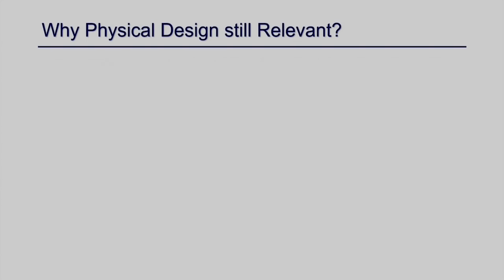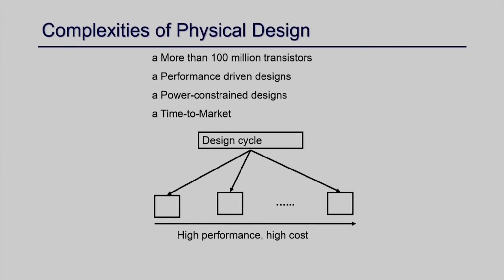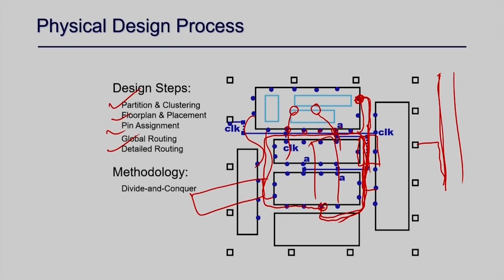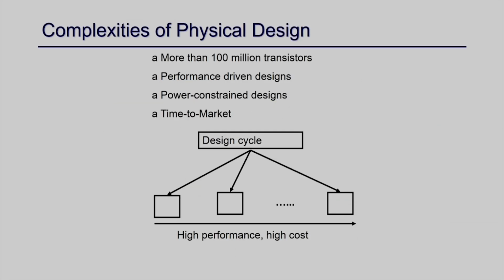And also one more important point has to be noticed here, that all these subtasks that I talked about, placement, floor planning, global routing, physical routing, most of them are kind of NP complete problems. NP complete in the sense they are not polynomial time solvable. They are kind of exponential. If you are trying to find an optimal solution for them, you need an exponential algorithm, right? But physically you can understand with 100 million transistors, it just won't work, right?